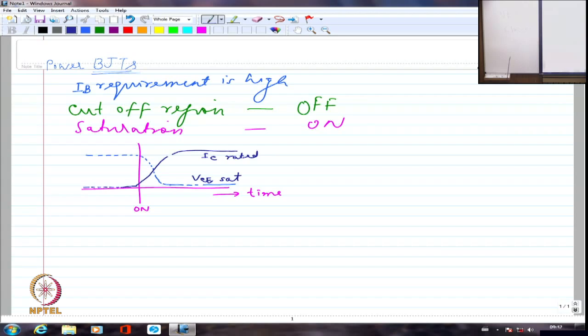In this particular region, if I multiply voltage and current together during this duration, these are the turn on losses. When I talk about turning on the device, whatever the device incurs as losses during turn on is the voltage multiplied by the current during the turn on duration. So it is the integral of VI dt. That will be termed the turn on energy loss. But if I simply take the product VI for the entire duration, that is essentially the power loss incurred by the device during the turning on duration.